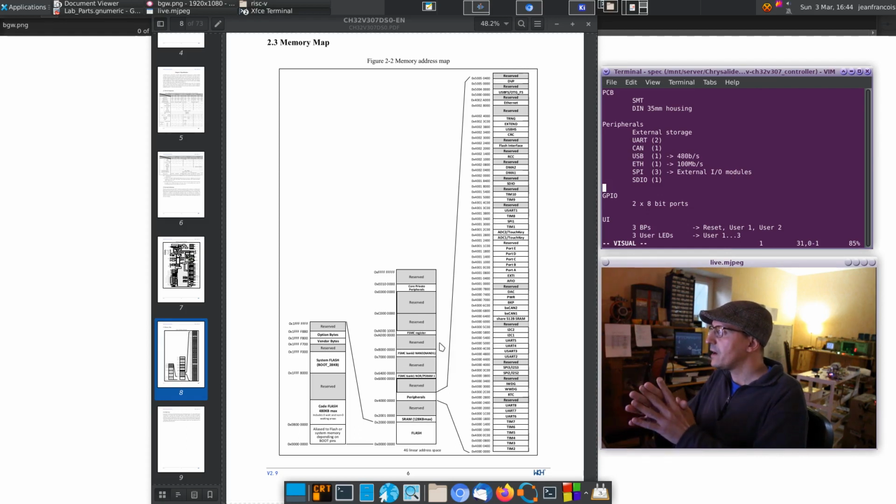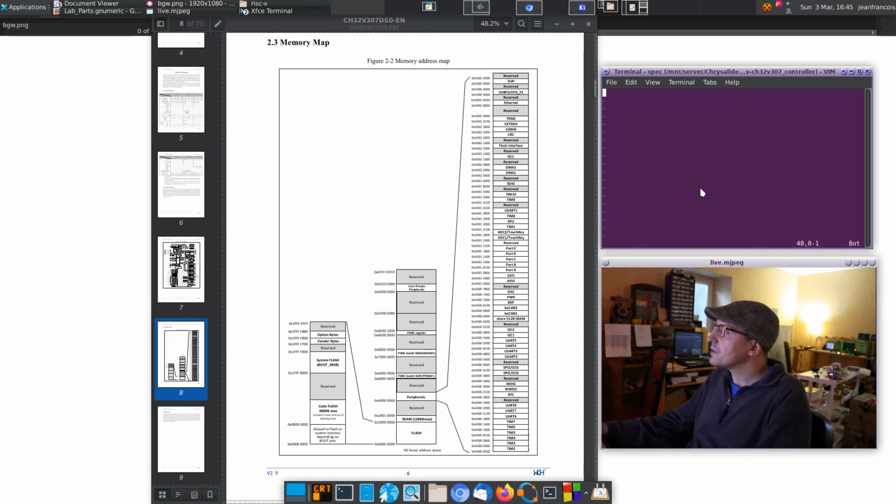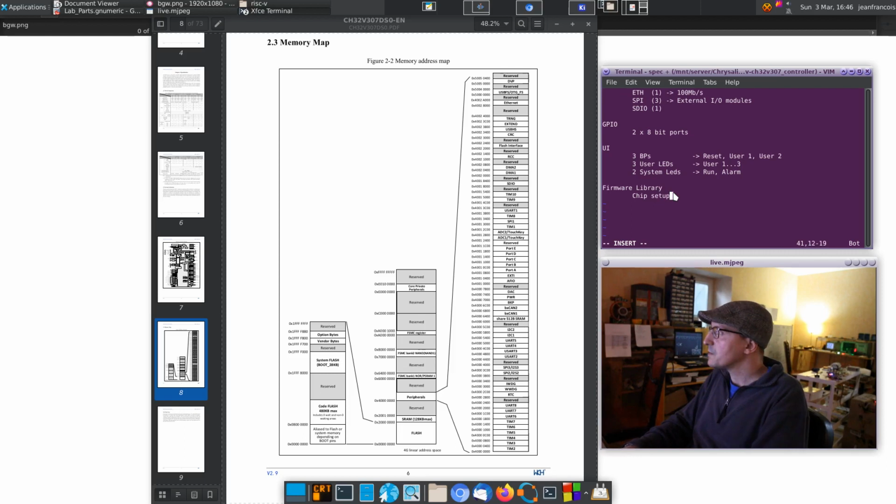There's a main file, a library that's most probably a C++ library to be called from a user program to change the direction and setup of the GPIO speed and direction, change the timers, use outputs such as PWM and digital, input and output as well as analog, and use the serial modules. So we'll define more or less what the library will need to do: chip setup, IO setup, IO control, and serial comms.